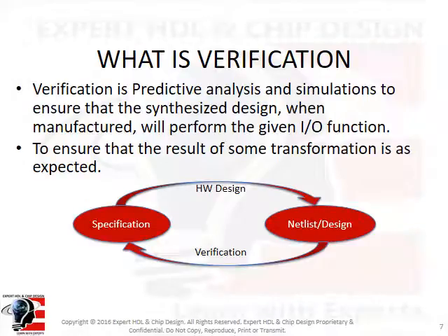A design is not ready until completely tested and verified. Also, it is not practical to wait until the whole chip comes back to test it completely on physical automatic test equipment. This can prove to be very costly. It is very important to run verification on a design before it is sent to the foundry. Verification should be done at every stage of the design cycle. Verification is the process of running simulations using CAD tools on designs to check if they meet the required specifications and functionality. The phase of verification run after silicon is back is called testing, done on automatic test equipment.